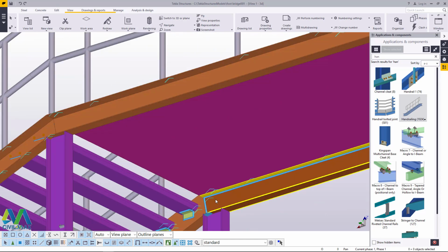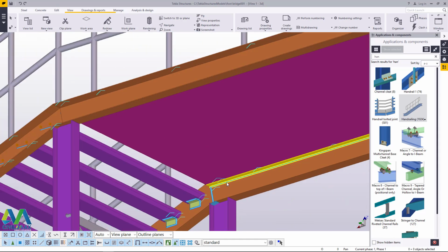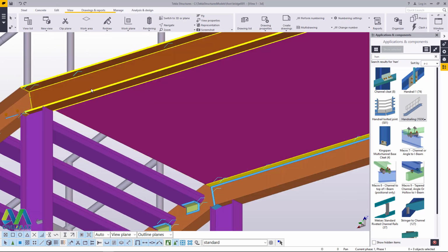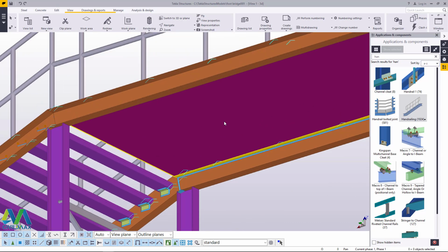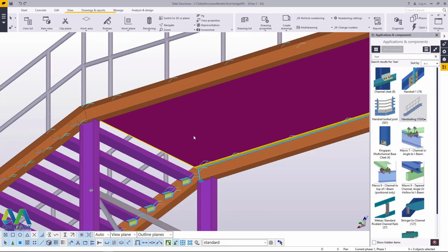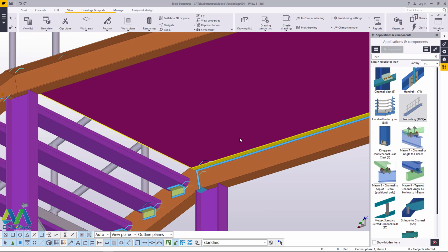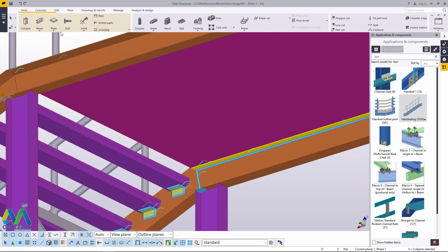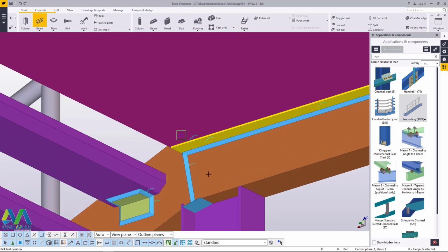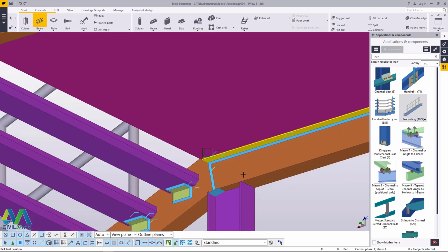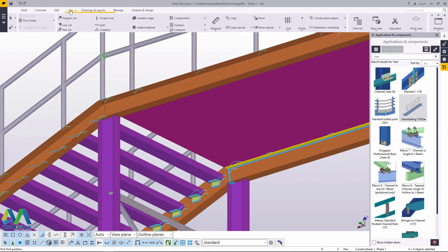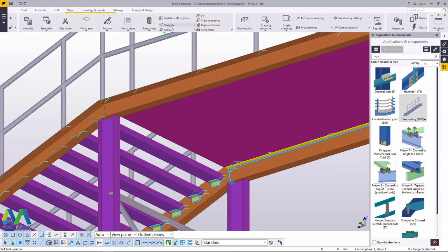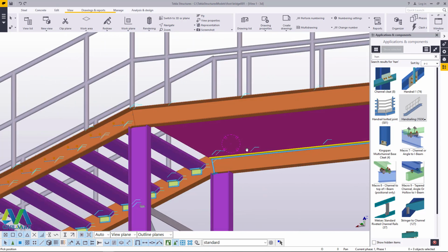Now we want to place some braces at the bottom end of this walkway here. What I'll do is come to Steel here, then Steel Beam, and pick the beam, and I want to pick a position where my placement will be accurate, and I have to get the points that will make it look accurate when I come to placing it. Perfect.